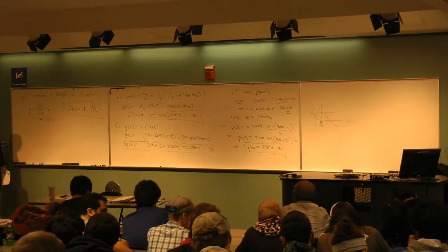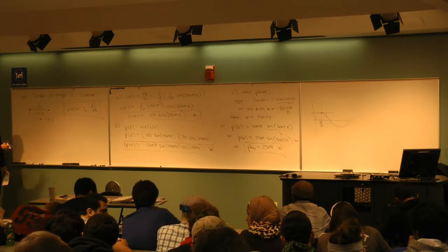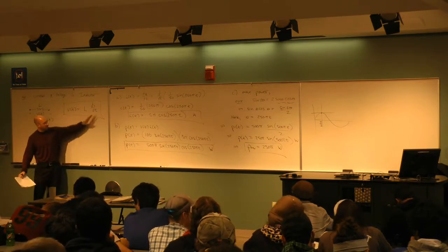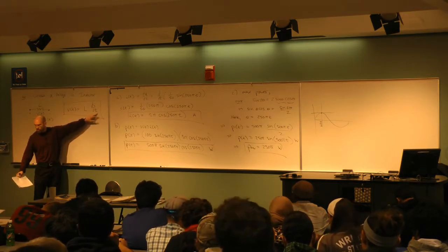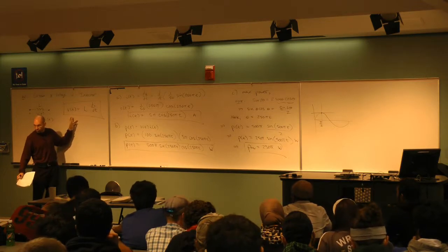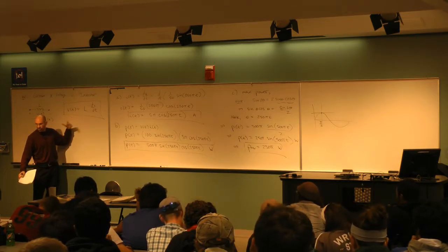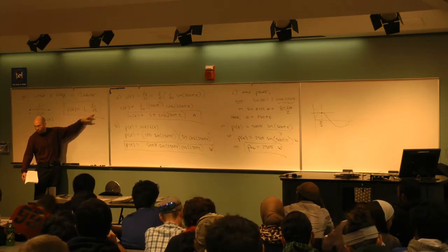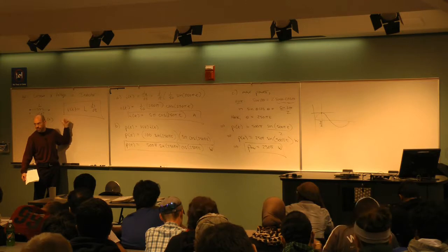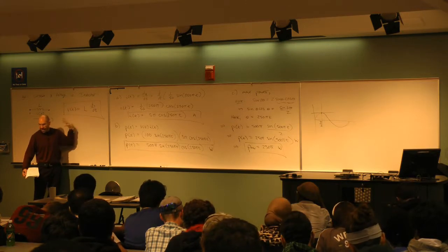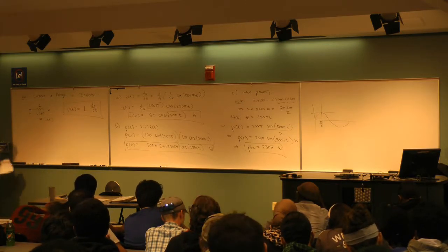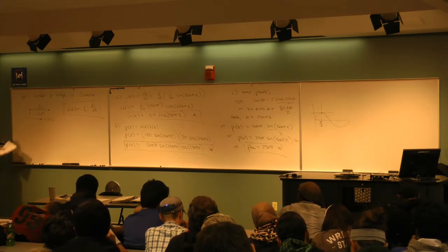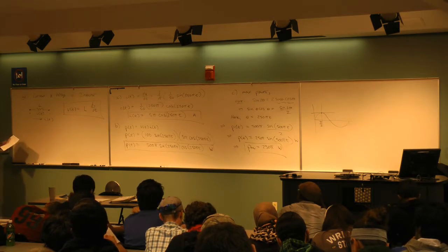What it means is that if I have an inductor in a circuit and I'm controlling one or the other, the voltage or the current, I can control the slope of what the current is doing by changing the voltage source. Similarly, if I change the current in a purposeful way, so I control the rate of change, that will control the voltage that I get across. So you can start stacking together these circuit components and make a circuit do what you want it to do. All right, so given this, let's answer this question.